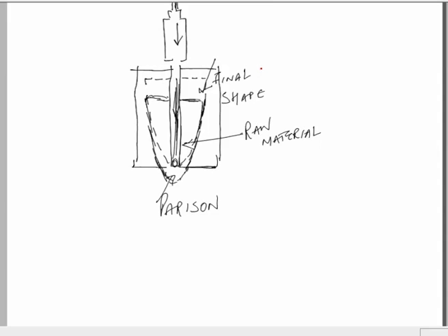It is a two-piece mold. We can say it can be divided into these two along this line. So it is a two-piece mold. When it closes down, the raw material comes inside, hot air is blown inside the raw material. Raw material is called a parison. It is a plastic part and under the influence of the hot air, this plastic part inflates and takes the shape of the mold. Most of the plastic bottles are made by the blow molding process.